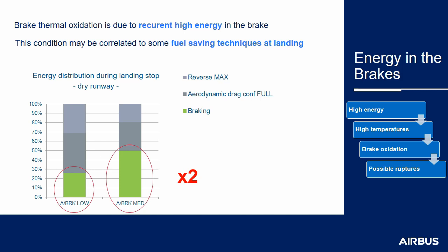As a result, the brake temperature will be much higher in autobrake med than in autobrake low. Consequently, the risk of oxidation in autobrake med is higher as well. The analysis was performed on the A320 family with associated autobrake modes, but the philosophy is applicable as well to A330, A340, A350 and A380.